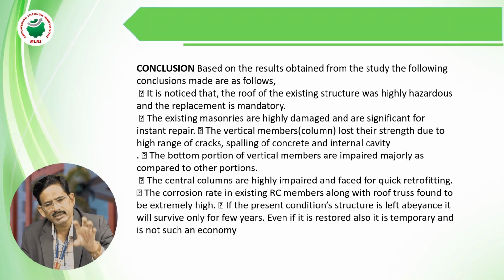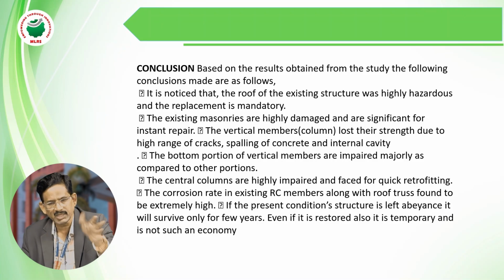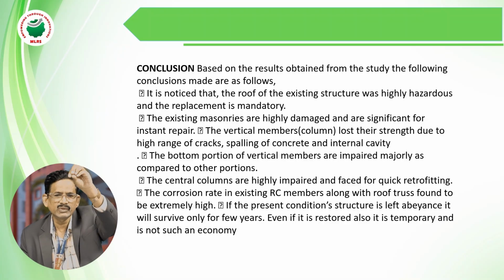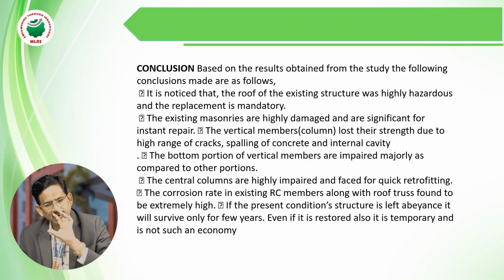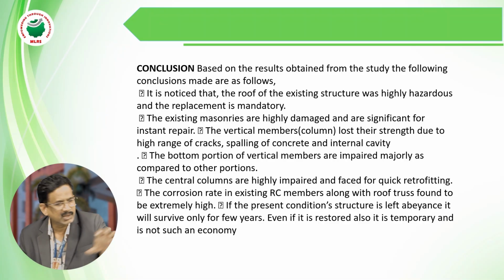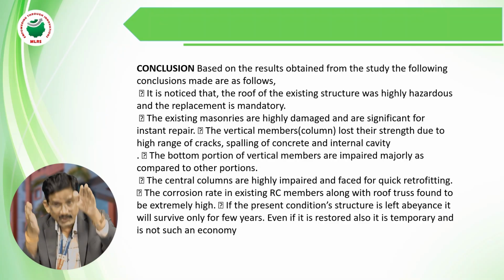You go to the site and see whatever defects you observe, whether in the columns or the beams or the slabs or the floors or the walls, brick walls or shear walls. First of all, we have to verify physically. After that, we have to take clear photographs. Then you have to pin them one to one and write whether it is a column problem, beam problem, slab problem, shear wall problem, staircase problem or floor problem, and how many floors there are.